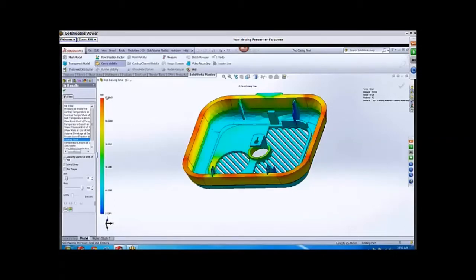So right now, we're looking at a cooling time of 60 seconds, or a little bit higher than that, whereas the fill time was 3 seconds or thereabouts. So this is a really, really significant time here. What we're going to try to do is reduce this as much as possible, hopefully get it around 30 seconds, if that's possible.